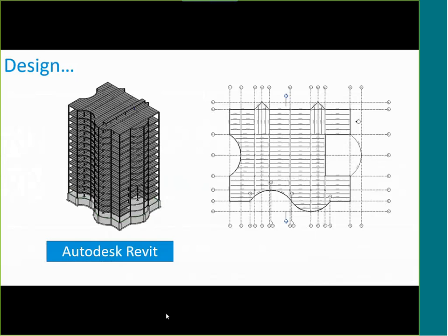So before fabrication, I would use Revit for all those things. So don't try to do documentation before fabrication in Advanced Steel. Really use Revit. The basic documentation in Revit's a good thing. It's so much smoother than creating them in Advanced Steel.